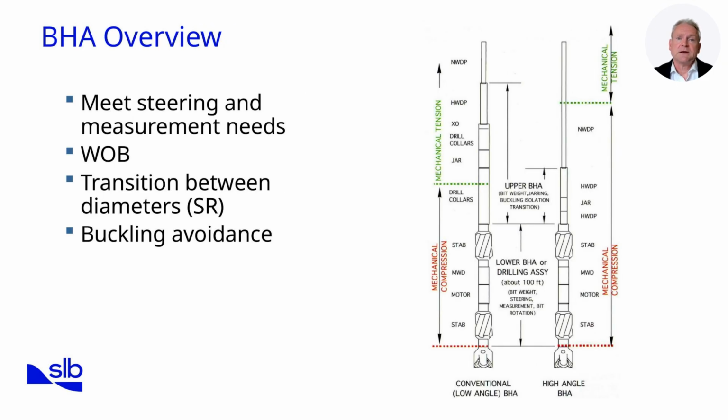The bottom hole assembly, or BHA, directly influences well trajectory and load transfer. It consists of drill collars, stabilizers, heavyweight pipe, and other specialized tools. The BHA must provide sufficient weight on bit to achieve penetration, while also guiding the bit along the planned path. Designing an effective BHA requires balancing stiffness and flexibility. Too stiff a BHA resists curvature and makes directional control difficult, while too flexible a BHA may buckle or allow the bit to wander, leading to poor hole quality.